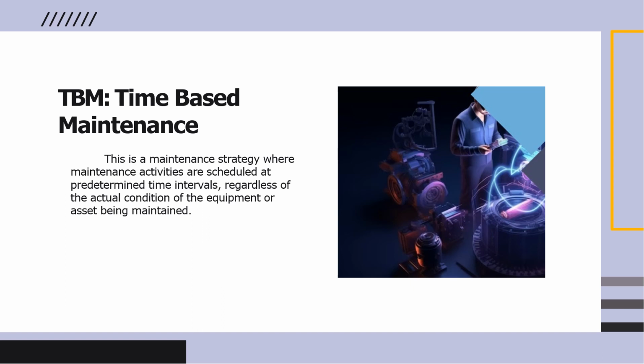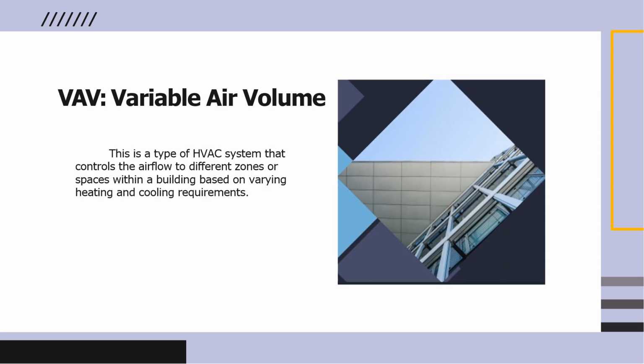For example, if you buy a vehicle, they might tell you that you should change the oil and other things once in 3 months or after a certain number of kilometers that it has been driven by. That's likened to TBM, time-based maintenance. There are other equipments that are like that. So it's different from actually doing a CBM, which is condition-based maintenance.